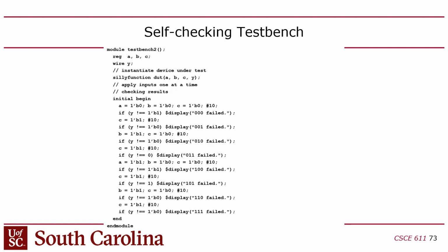So you could print a little error message. So the idea here is that you essentially just load this in the simulator and run it, and if it doesn't print anything, then it's working. If it prints an error, then you have to bring up the wave window and start drilling and trying to do some forensics, find the bug, right? But if it doesn't print anything, assuming of course you ran it long enough, how long do you have to run this for, by the way?